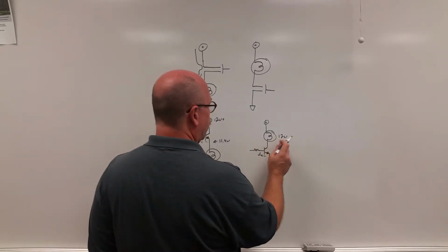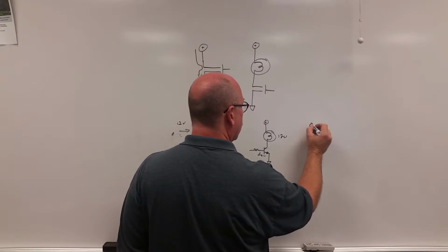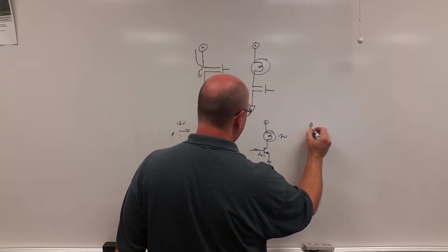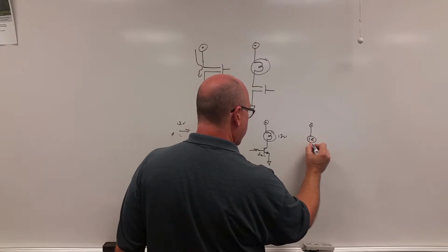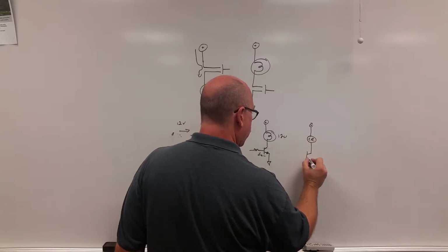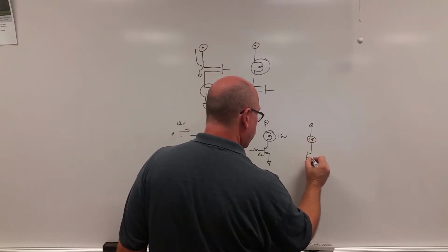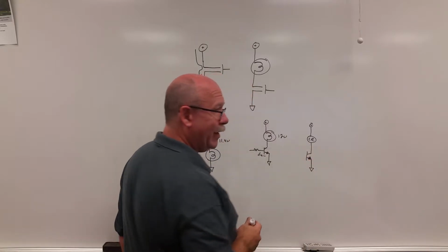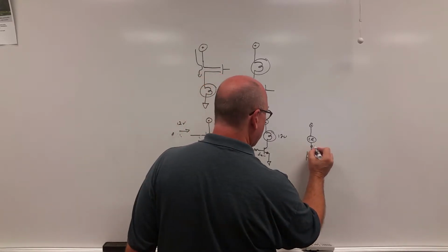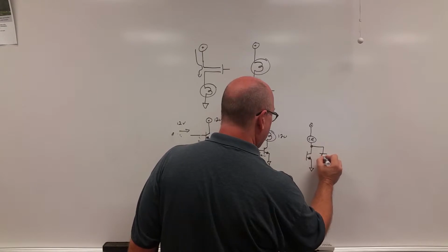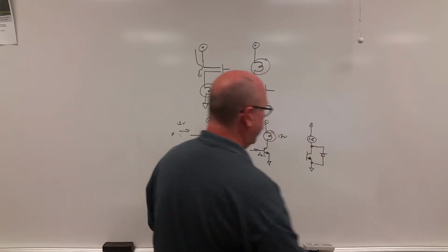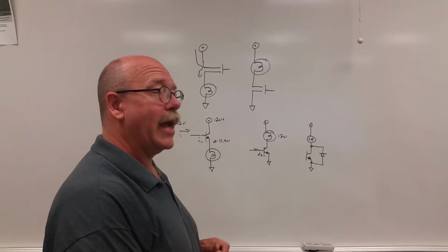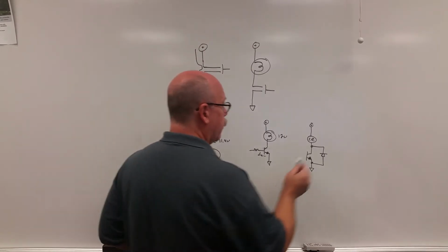So in this situation, when you see relays being driven on outputs, particularly of PLCs, and they're driven with a transistor, they're typically in sinking configuration, and you also have a protection diode that sits on the output of it to protect against back EMF when the coil is released.